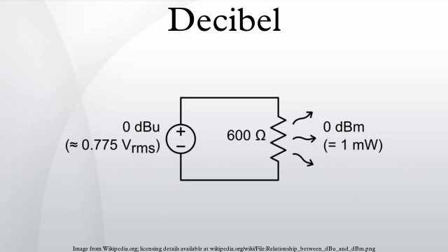before clipping occurs. Full scale may be defined as the power level of a full-scale sinusoid or alternatively a full-scale square wave. A signal measured with reference to a full-scale sine wave will appear 3 decibels weaker when referenced to a full-scale square wave, thus, 0 dBFS, ref equals full-scale sine wave, equals -3 dBFS, ref equals full-scale square wave.